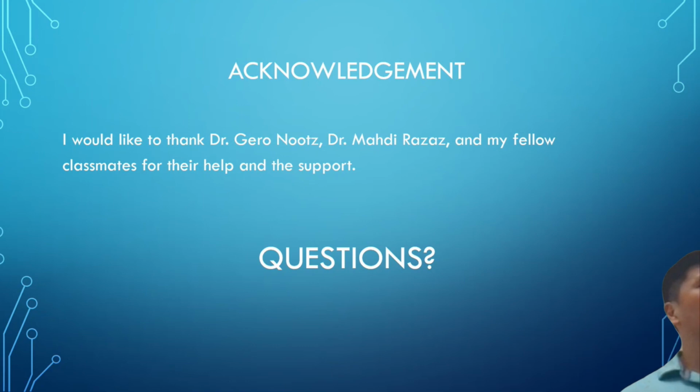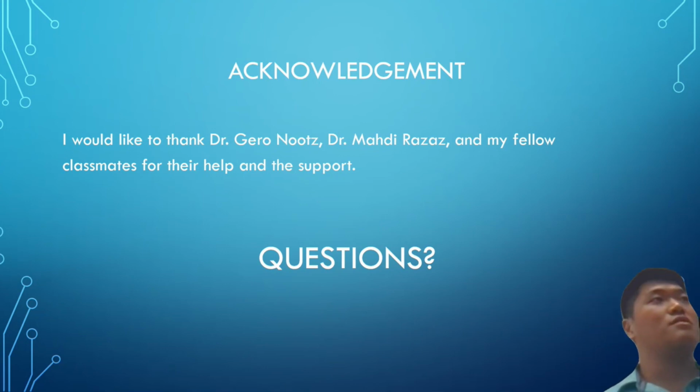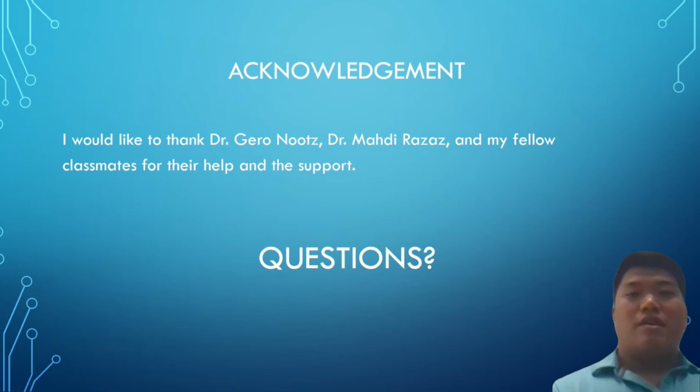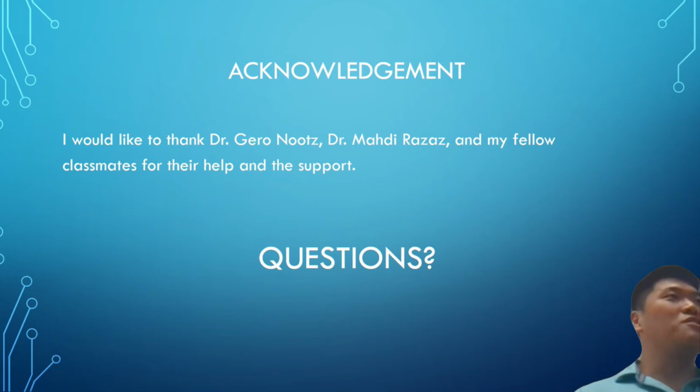Follow-up question actually. What would you do to extend your range? The range of your communication device. Multiple things. I can push more voltage in there, or I could redesign my coil to have more turns or a larger radius, so bigger diameter, or I can also use a different wire size. So yeah, that will all contribute to extending the range. And also maybe possibly a relay, like a range extender, so I have another coil in between.